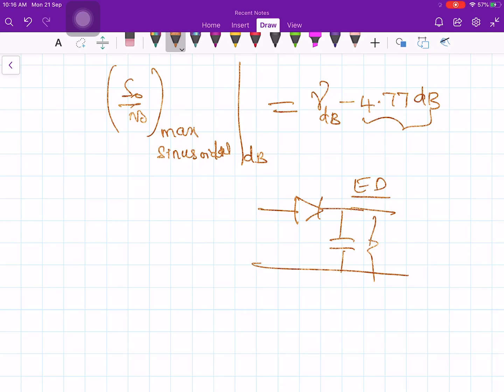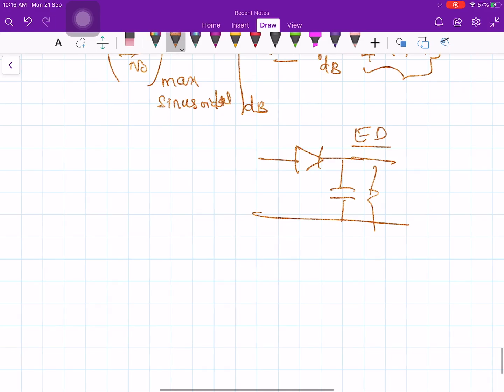Therefore, the output SNR that you have calculated is for the situation where the demodulation is synchronous. Okay, so as I said, actually we transmit carrier so as to get the simplicity of the demodulation, not to have to use synchronous demodulation. So the next question is, would the envelope detector give you the same performance as the synchronous detector does, or as the coherent detector does? That is the next question we are going to look at. Now let us look at AM with the envelope detector.